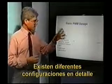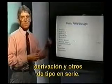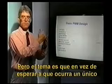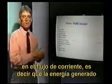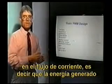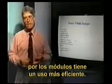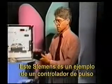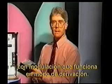There's different detailed configurations of these types of controllers. Some of these are shunting type, some are series type. But the point is, instead of waiting for a single set point to occur before some action is taken, there's a continuous variation in current flow, which is, in a sense, a little more efficient use of the energy generated from the module. An example of a pulse width modulation type of controller is this controller made by Siemens that involves a shunting in a pulse width modulation type of mode.